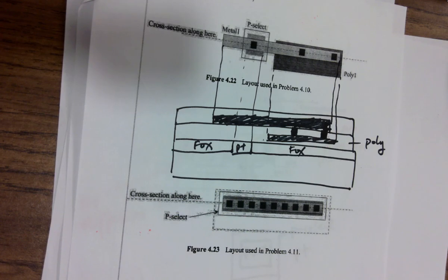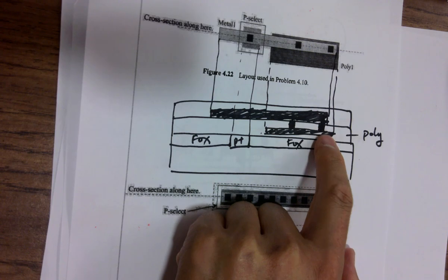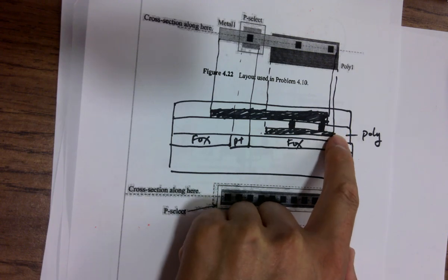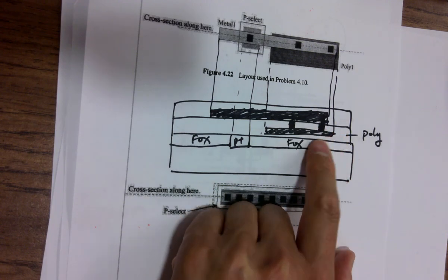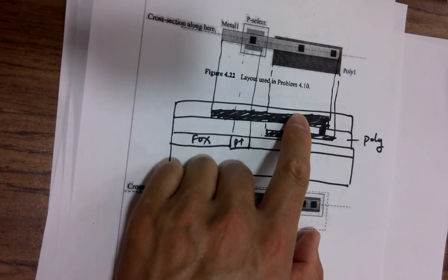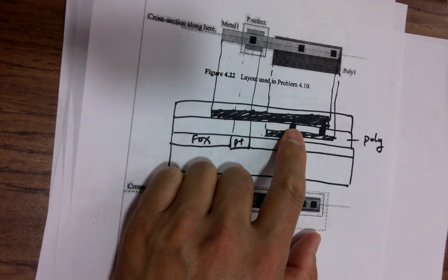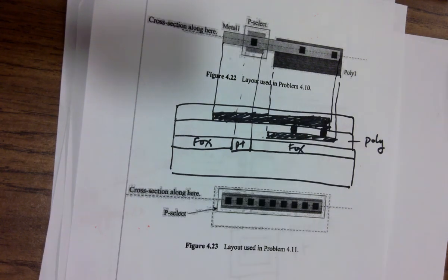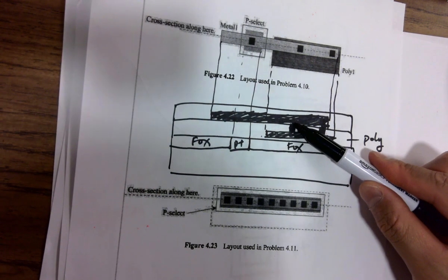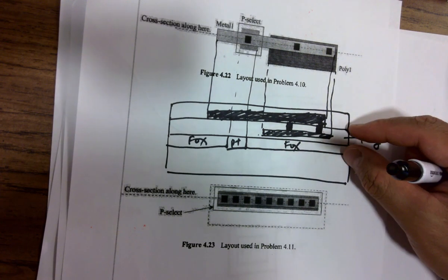It's doing everything layer by layer. The height of the via actually defines the layer's thickness of the poly layer, right? You're thinking about, can we just have this one intruding into the metal 2 layer if metal 1 is not touching the bottom? I mean, wherever the via stops, it defines the width or the height of the metal 1 layer.